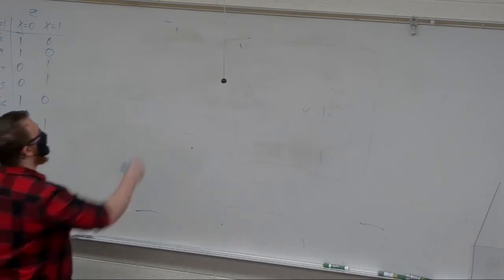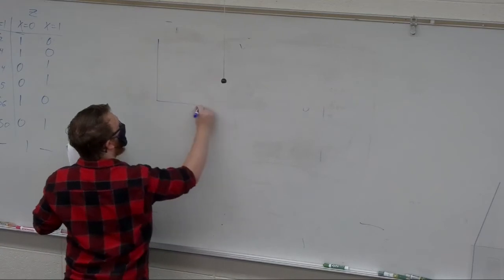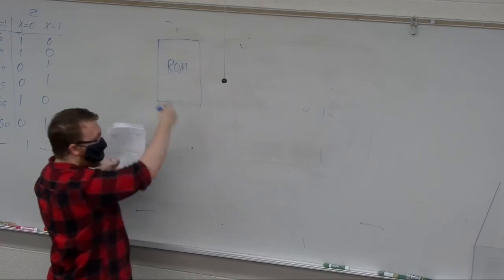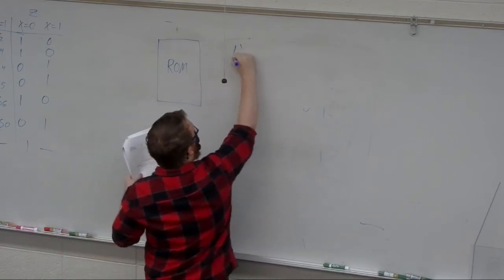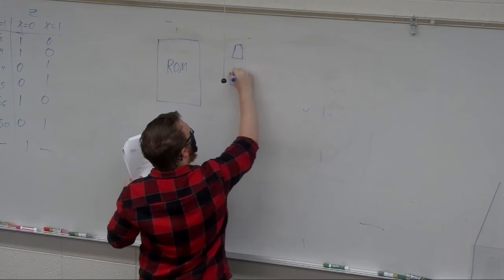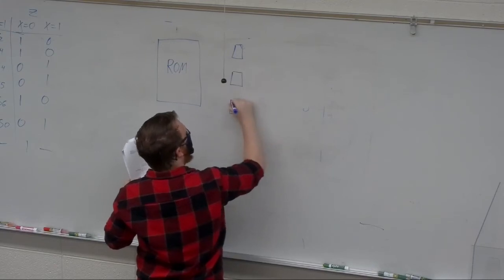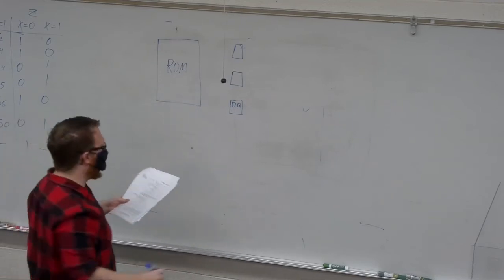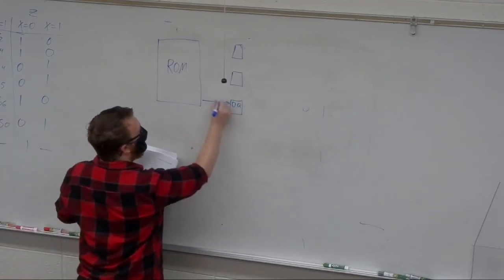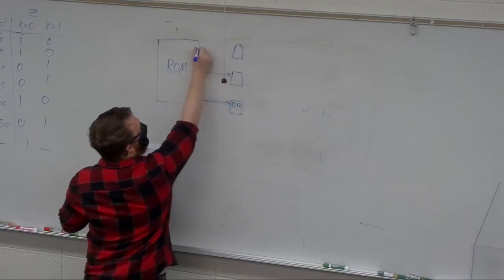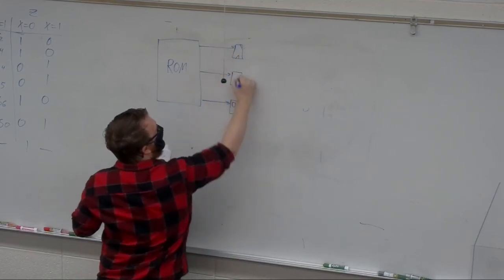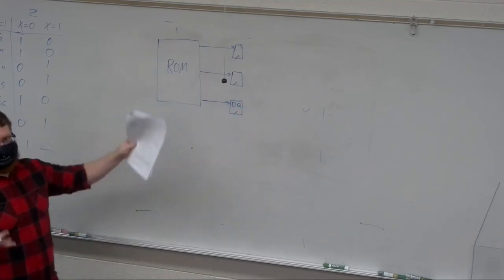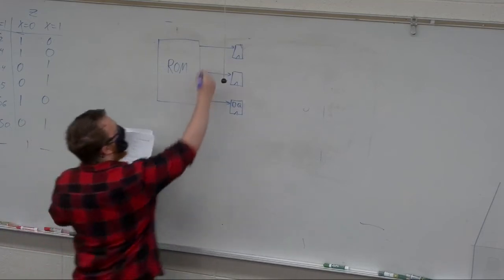So the way you do that is you take a ROM, right, which is just lookup tables. You hook it up to some, these are all just D flip-flops, DQ flip-flops. You throw some of the outputs into those. You of course have to clock all of these, right? But I'm not going to draw the clock, just to keep it a little clean.